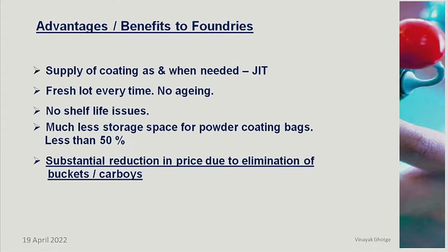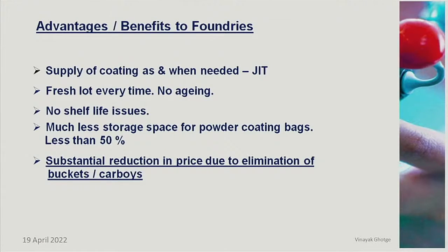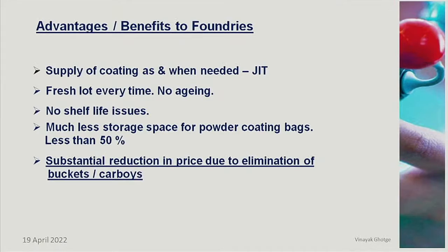What are the advantages of using powder coating versus ready for use or paste form? The coating is supplied just in time, a fresh lot every time, so there is no aging, no bacterial attack, no shelf life issues. And the most important from a storage point of view is that less than 50% of the storage space is required, because these are all bags which can be stacked one over the other. The powdered product has a shelf life of 1 year, and unless it is tampered with or gets mixed up with water, the product doesn't deteriorate. So there are absolutely no shelf life issues.